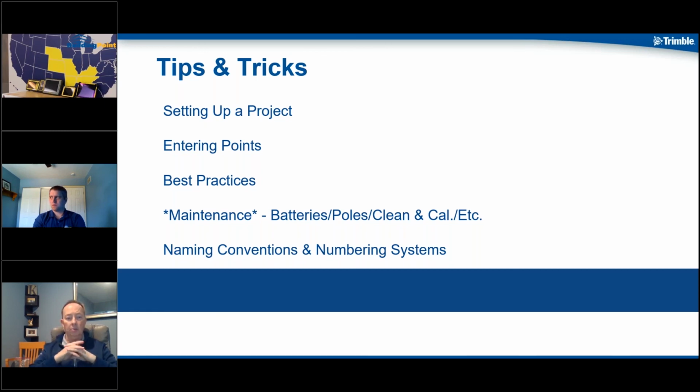Entering points. We talked about some of that already with Sean, the way he was talking about it, but you can manually enter those points by going into the point manager. And if you've got the data, maybe you've got a control point that a surveyor or someone supplied you with, you can go in with that little pencil and paper and manually enter the XYZ or the NEZ information in there, and it's going to show up on your tablet.